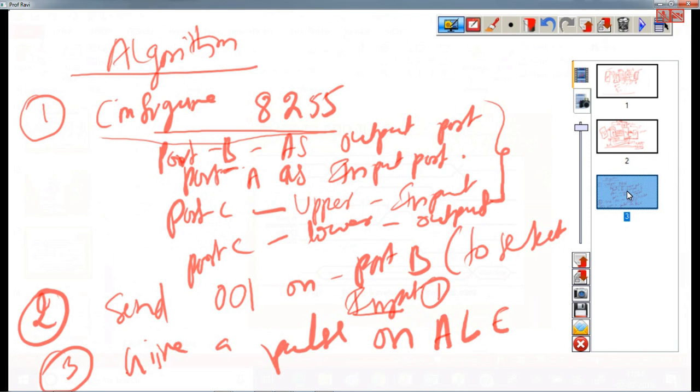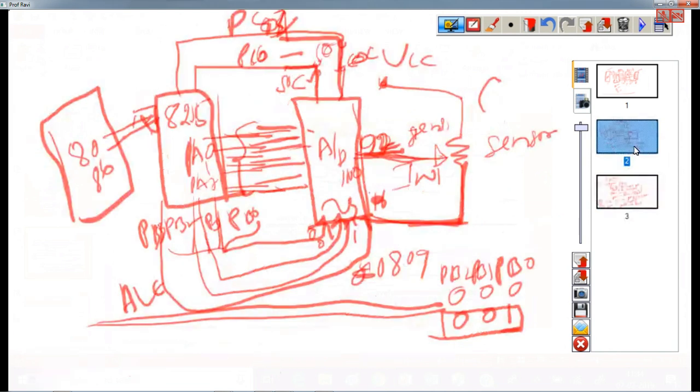So bit programmable way you can go ahead, or otherwise you can use port B3 and generate a square pulse. Instead of connecting it to PB3, you can connect it to PB4, not to disturb the selection lines PB0, PB1, PB2.